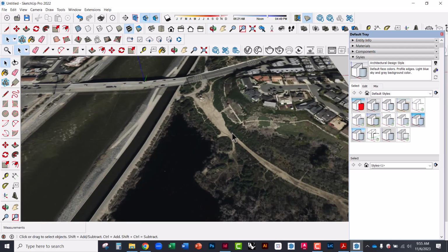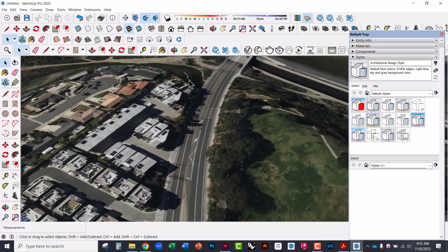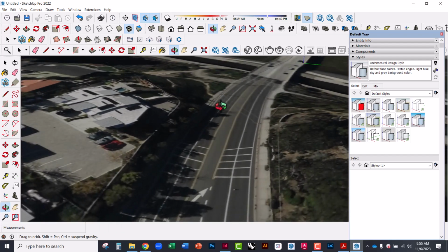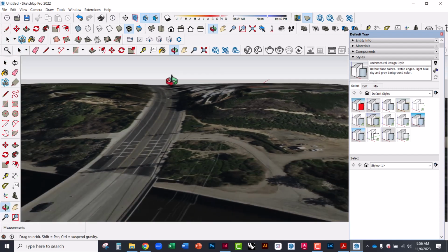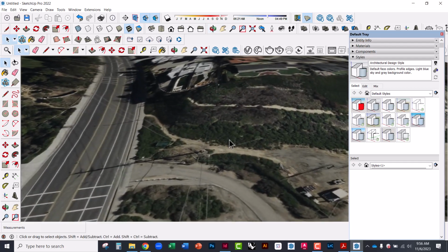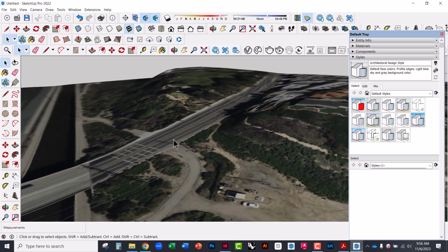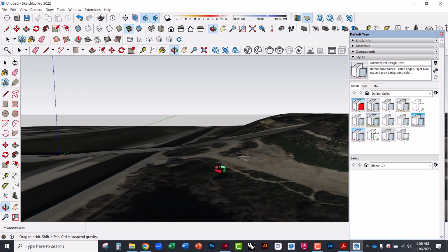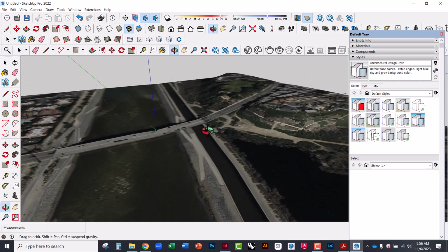And you can see when you zoom in that there's actual texture to this. Not extremely accurate as far as topography, right? That's obviously a flat street, but it's enough to give you kind of an understanding of the terrain, and gives you enough that you can start slicing this in Rhino. So, what I would do is model the street, model the roads that obviously are flat, but use the topography that you import from this.